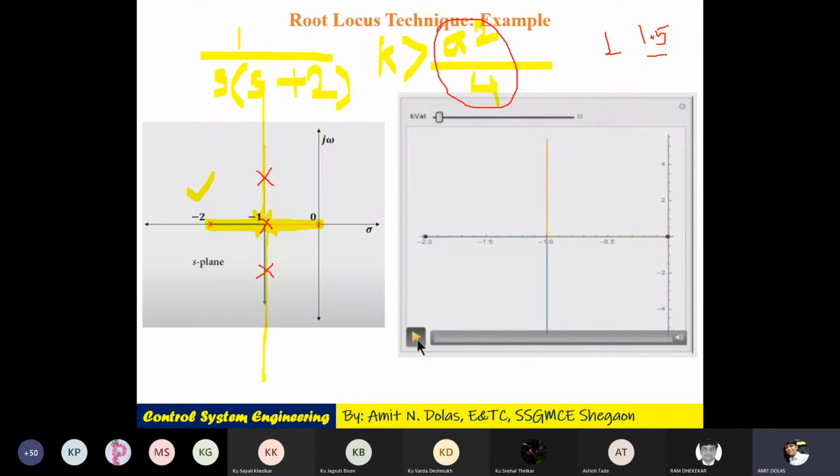If k is equal to 2, you may get another value, and again the replica of that. So you can see, if I change the parameter open loop gain k on the root loci, S2 will follow this line, and S1 will follow this line. It will not be beyond this particular graph.